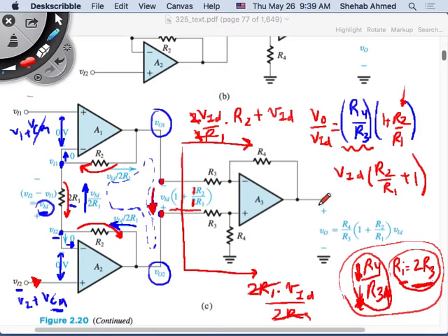So I have a very nice circuit now, right? I have infinite input impedance, zero output impedance. I'm rejecting common mode, and I'm applying a gain, and I'm not dependent on tuning these resistors for the common mode rejection. Remember that tuning these resistors was a problem with the common mode signal passing through, right?